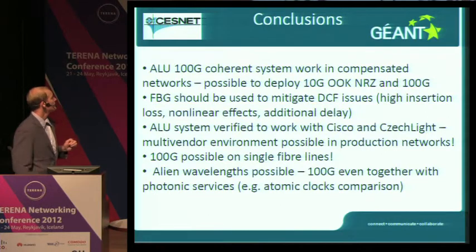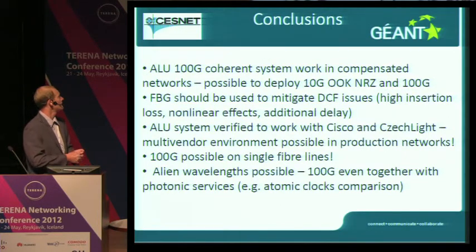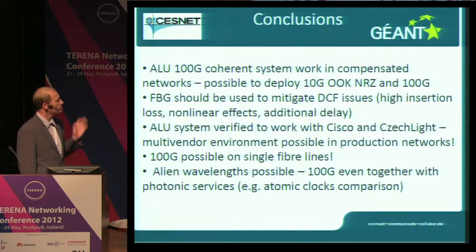So to conclude this, we would like to highlight that ALU 100G, Alcatel-Lucent 100G coherent system is working over compensated networks. So we don't have any worries about deploying it in our network where we have the dispersion compensation. We would recommend to use fiber Bragg gratings rather than dispersion compensation fiber, because dispersion compensation fiber has a higher insertion loss, nonlinear effects, and some additional delays because of the length of the fiber.